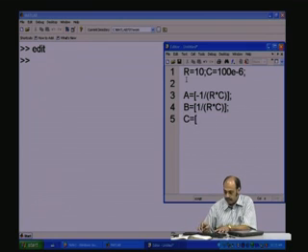and the C matrix in this case is 1. We will see the C matrix will change depending upon what you want to monitor, what you want to sense, and we will probably sense some other variable later on and then see what happens to the C matrix and the D matrix. And the D matrix is in this case, for this particular output that you want to sense, that is the voltage across the capacitor, is just 0.